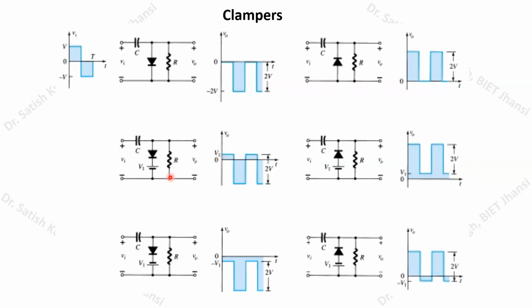And then in the negative half cycle, one more thing that you can calculate is what will be the maximum voltage up to which this capacitor is going to be charged. Okay, so here you can see it is V1. So here if the applied voltage is V1, as we have seen, it is equal to capital V here. Okay, so when the capacitor is going to be charged, the maximum voltage will be equal to capital V minus V1. Okay, that will be the voltage by which your capacitor will get charged.